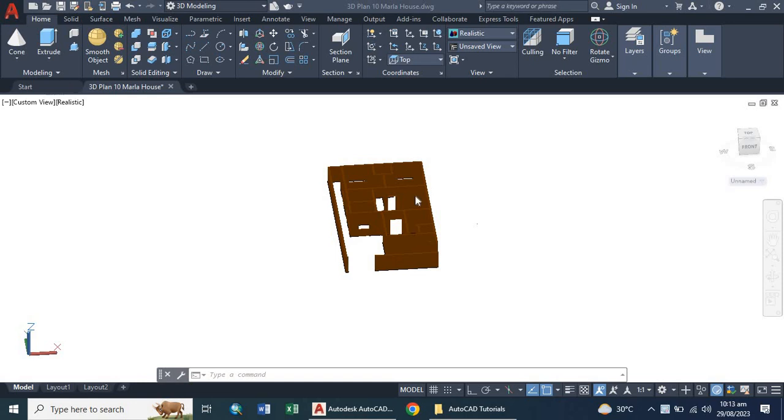As in the previous video, we have already discussed the creation of spaces for doors and windows. In this video we are actually creating and designing a door, and we will be fixing different kinds of doors here. Let's get started. First of all, when you have to create a door in AutoCAD 3D, I recommend you create an extra layer of doors 3D.